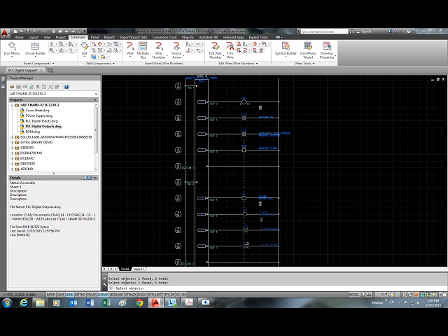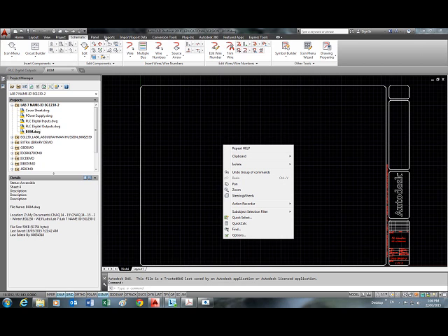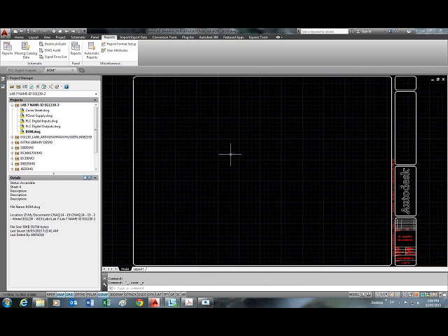And you could have done them straight just to see. I think that AutoCAD recognizes all of them even though the line doesn't go down. Again, always save. Let's go back to BOM and go to reports. I didn't save previously and it did crash during the catalog lookup, so again, be patient, and as I said before, save every now and then.